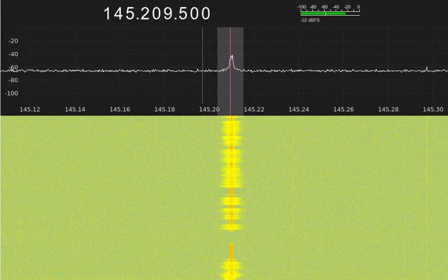How can overload of a non-amateur radio or TV receiver by an amateur signal be reduced or eliminated? A. Block the amateur signal with a filter at the antenna input of the affected receiver. B. Block the interfering signal with a filter on the amateur transmitter. C. Switch the transmitter from FM to SSB. D. Switch the transmitter to narrowband mode. A. Block the amateur signal with a filter at the antenna input of the affected receiver.